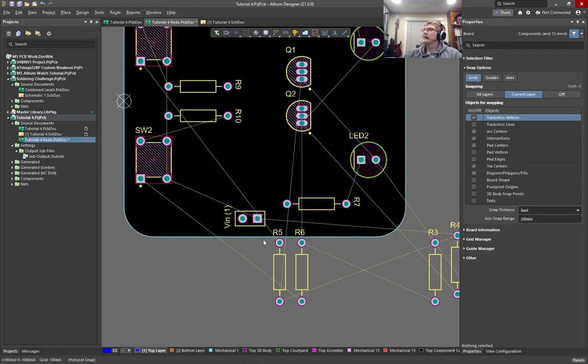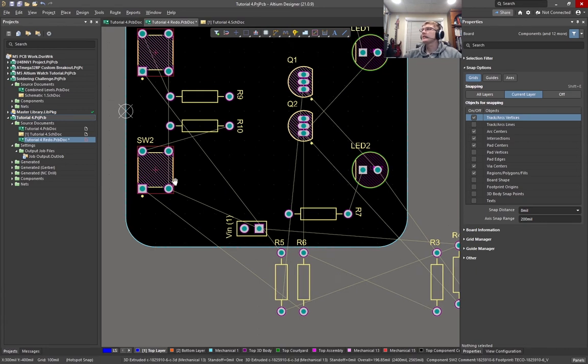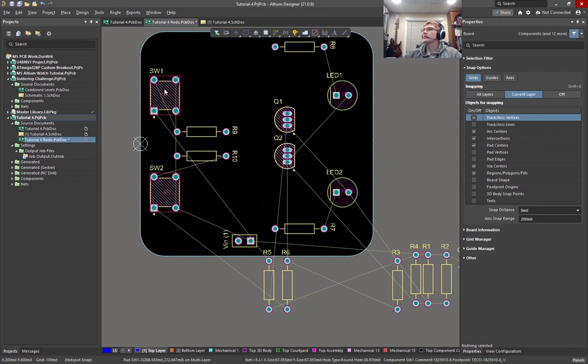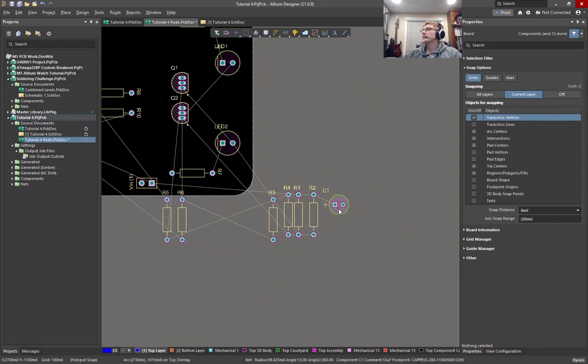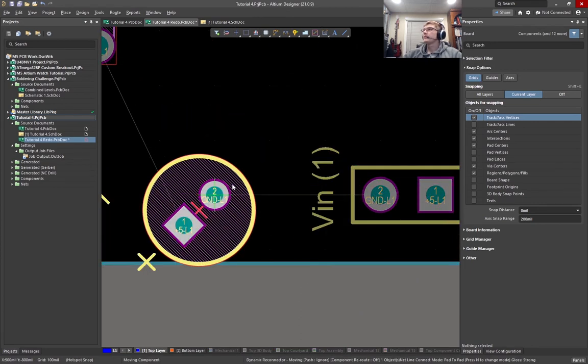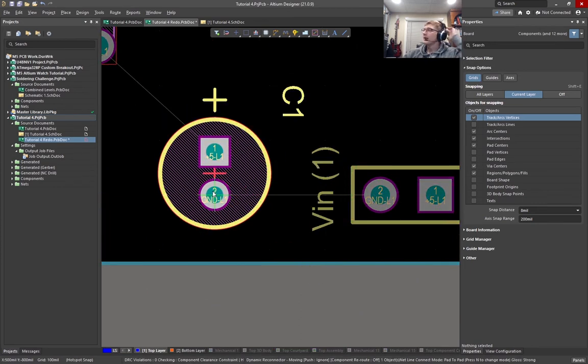Right, so it makes sense to have this on its own, close to an edge, so it's easy to give power to the board. It makes sense to have these both be on the same side so that it's not confusing to a user. These are things you want to consider when you're designing your board, which is most likely a lot more complicated than this. If I rotate that, I think it makes sense.